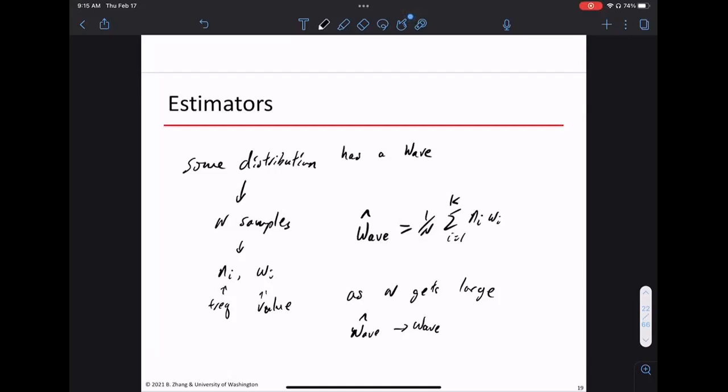To make this happen in practice actually takes some effort. So let's say you try to find a site that you want to build a wind turbine. You try to get some understanding of what the average speed is. Right? You have some finite budget of measurement, so you cannot measure every hour of every day for 5 years. So how will you actually go about measuring this kind of thing?